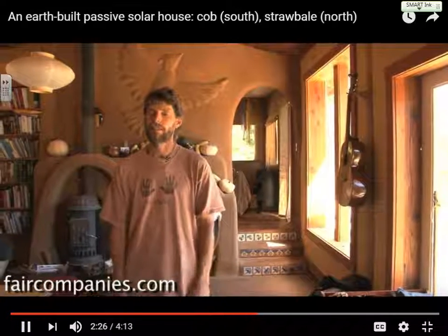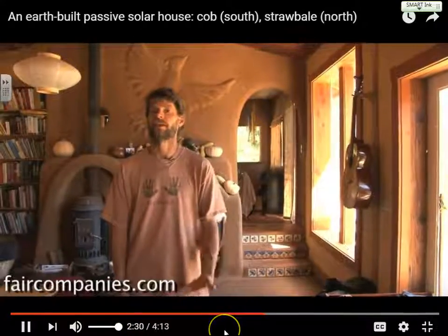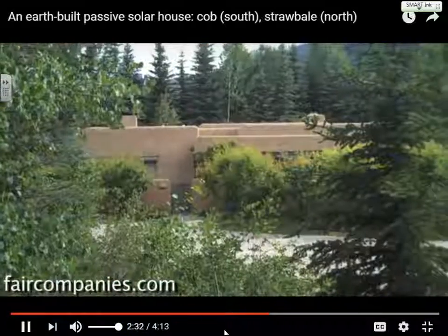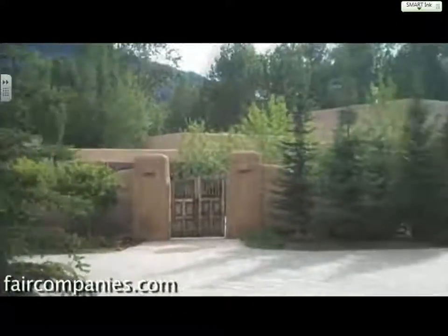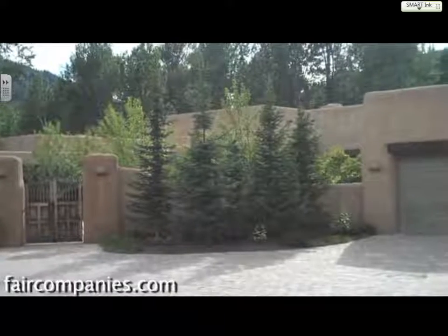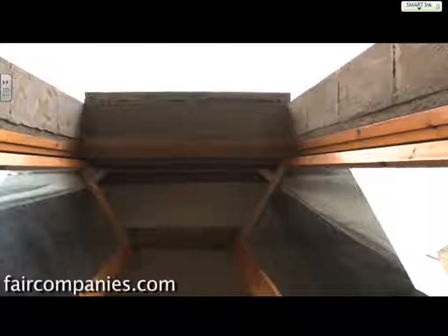So it's a really, really effective way to cool a house, particularly in a dry climate like this. Historically, if you look at hot desert architecture anywhere in the world, what you see is really thick masonry walls made out of earth usually or stone. Those walls hold the coolness from the nighttime and very, very slowly heat up during the day.